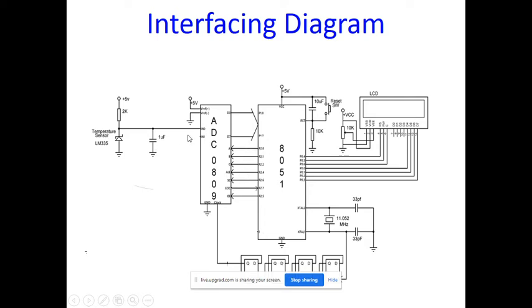Now to select one of the channels, there are the ABC 3 address channel selection pins. When you want to select channel number 0, you place A0, B0 and C0. When all 3 are 0, you are interested in channel number 0.